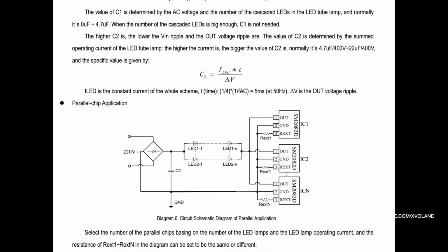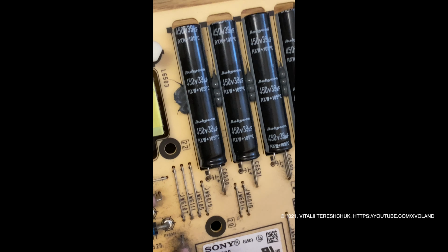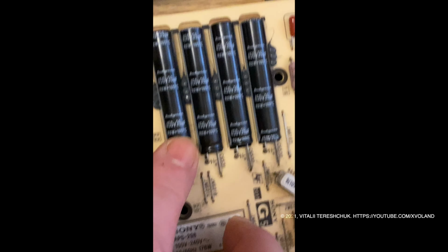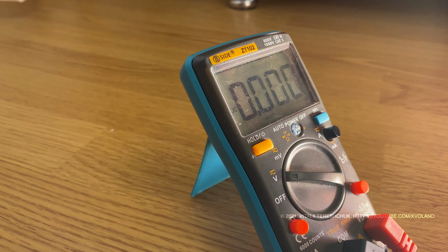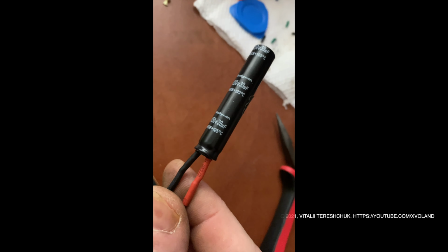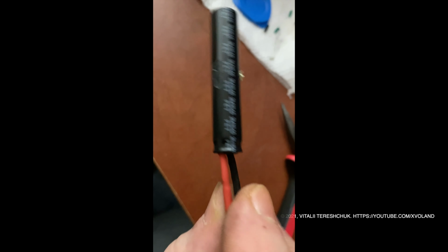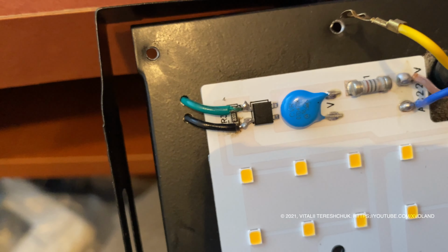I dismounted a 40 microfarad capacitor from an old TV board. That's a lot for this driver. I think 5, maybe 10 microfarads should be enough. Since the capacitor is too large, I moved it to the back of the LED panel and insulated the contacts.